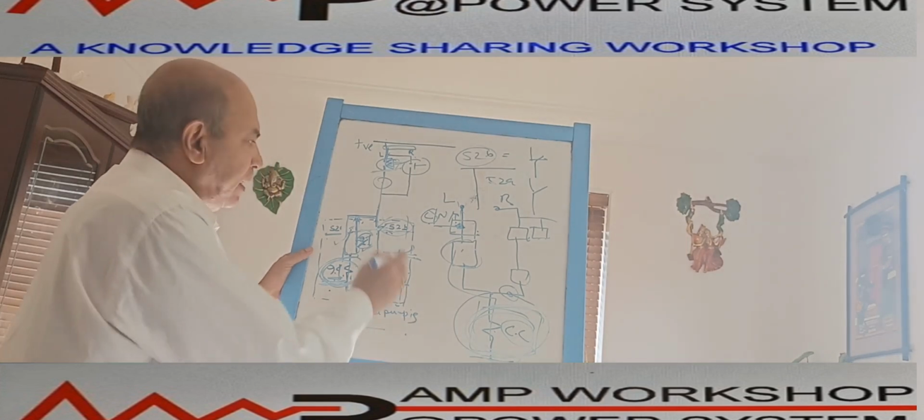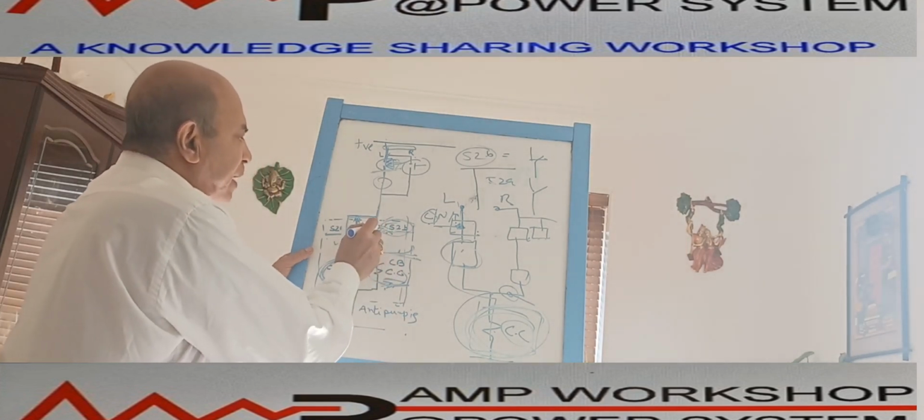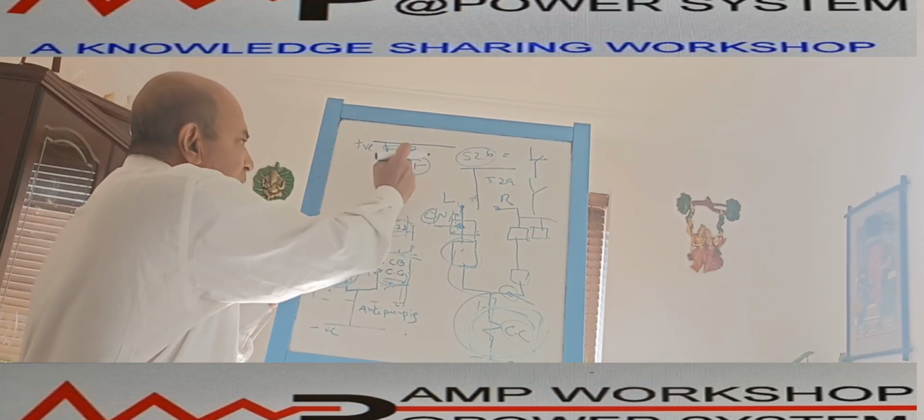The moment it is energized, it becomes open. It becomes open, it is fine. Then if there is a fault, it will immediately trip and become NC again. It becomes NC, and if you maintain the command at that time, it will close again. So if there is a fault on the circuit, or an unsynchronized closing command, and you maintain the command, then the breaker will be continuously closing and opening.